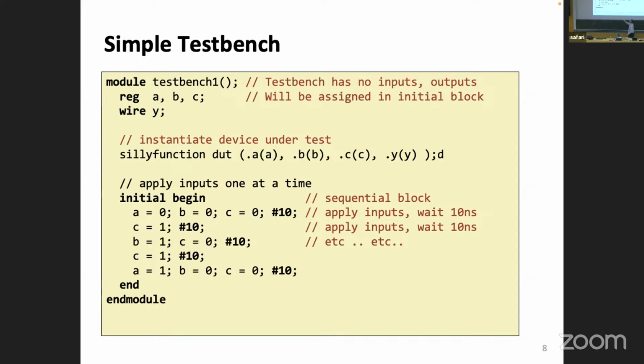What is the unit of 10? Well, technically speaking, at the beginning of the Verilog module, I could define what my time unit is. I could say, you know what, 1 unit should be a nanosecond. Then I could also specify my resolution, and say, let the smallest time step be, I don't know, 100 picoseconds. There are always some defaults, and in these examples, you will always see nanoseconds because it's a value that is close to the values of the technologies we use these days. They can be changed. We are not talking too much about that. You can always assume they are in nanoseconds. If not, you will be notified or there will be some comments explaining how we changed that.